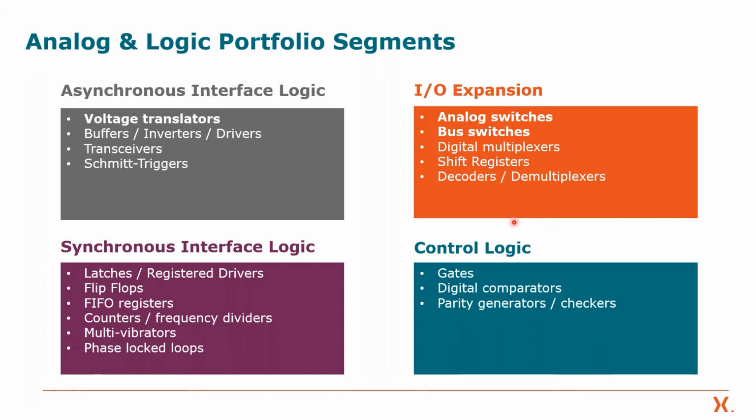Use 2 pins to shift serial data out to an external logic device and then have it shift data out on an 8-bit port, a serial-in parallel-out shift register, for example. It's more cost effective to have those pins on the external logic device connected to the external devices it's driving than to connect them directly to the microprocessor. So there's a lot of growth in that particular market as well.